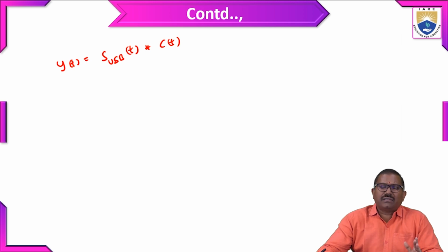That we can call coherent. The same phase information is used to recover the message signal, both transmitter and receiver using the same phase information. Clearly, that is phase synchronization. Such type of detection can be called coherent detection. Okay.